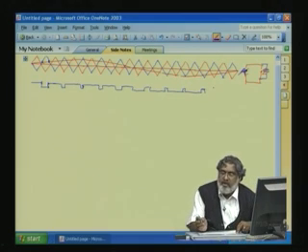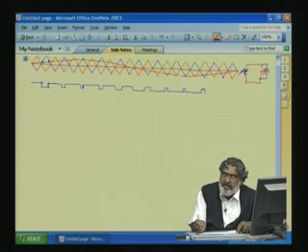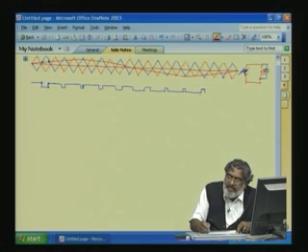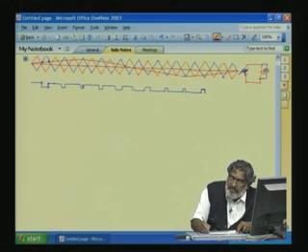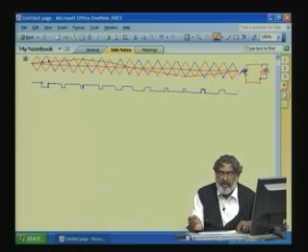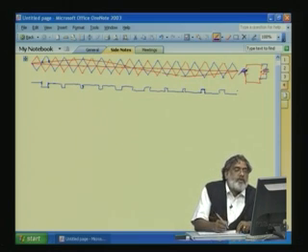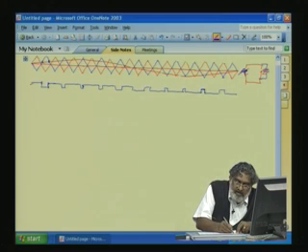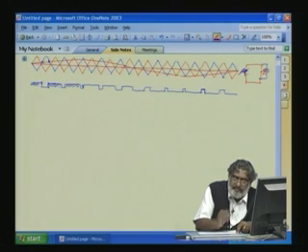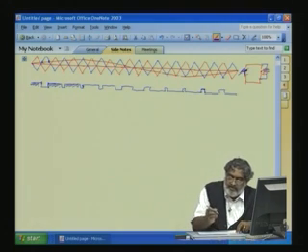So, the leg voltage or the pole voltage A with respect to our fictitious center point of the output DC is plus VDC by 2, otherwise it is minus VDC by 2 when the bottom switch is on. The waveform will look like this.